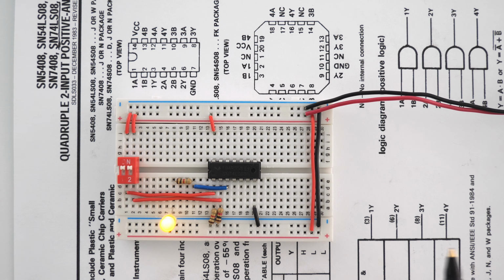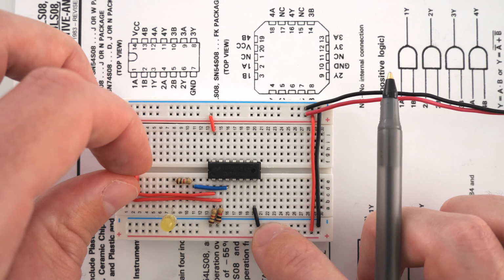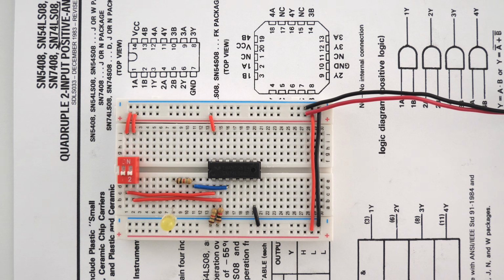So right now we have the inputs coming from this positive 5-volt rail through the switch, through these red wires, and into input A and input B. So this is how you would think of the circuit working, where we have a positive input into A and a positive input into B, which is why we have the output being turned on. Now whenever we turn off one or both of these, the circuit turns off, which is what we expect.